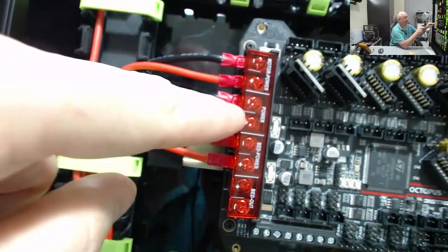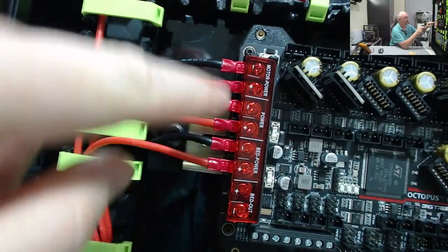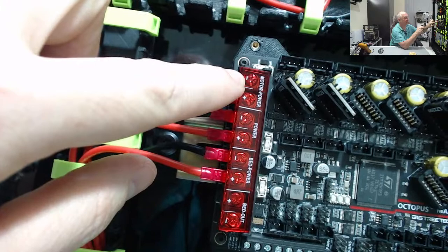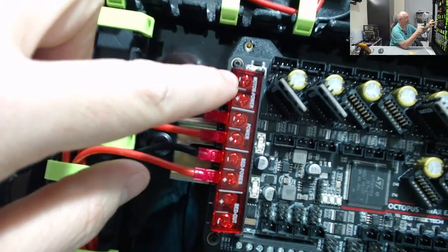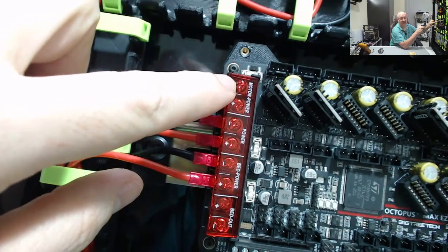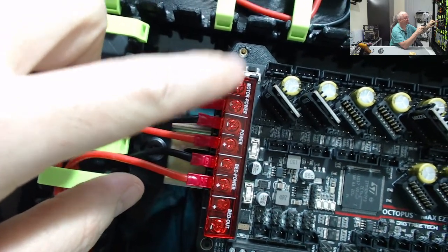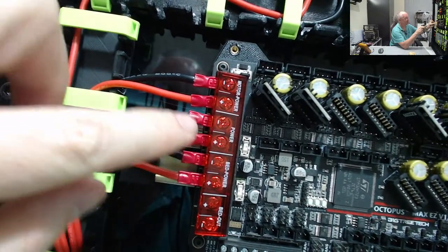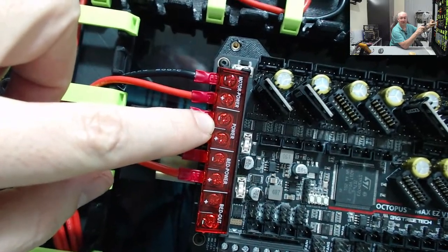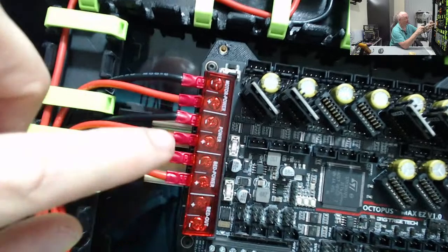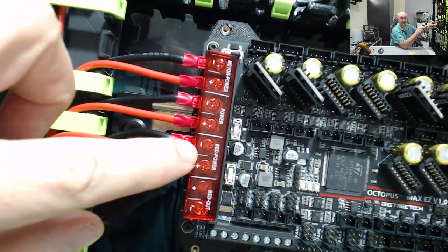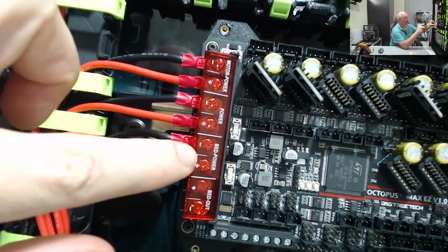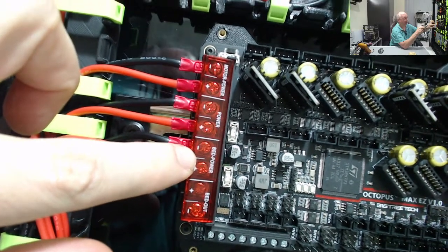You'll have motor power and bed power, right? On this board, you can give different voltage. Let's say you're running higher voltage motors. You can run up to, I think, 58 volts or close to 60 volts, I'm talking under correction, but in any case, you can run higher voltage motors. Yeah, I think maybe it's 48 volt. I need to double check. I've never run the higher power motors. Then your normal power is what goes to power the board, and the next one is your bed power. So if you're running a different bed power to the power that you're running in, you can potentially change that voltage slightly up and down, right?